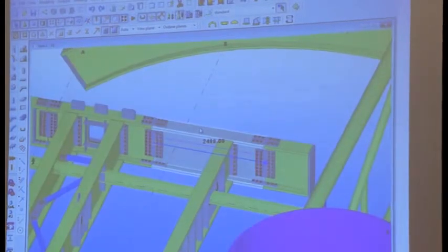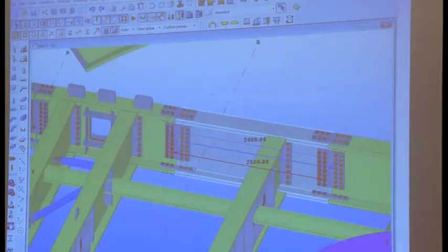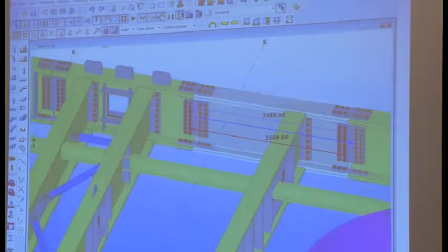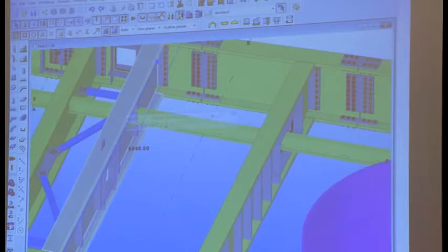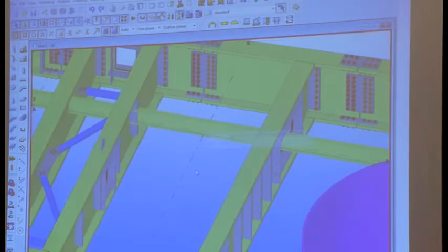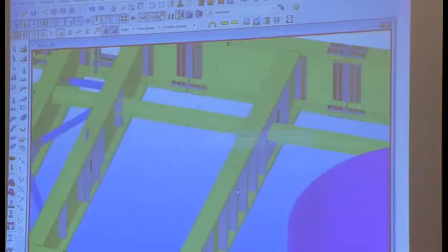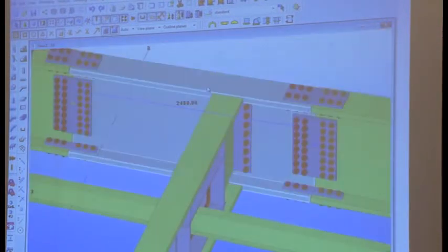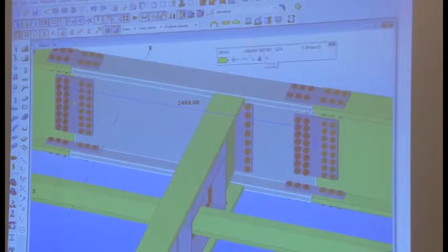Right, there is a beam with very heavy splice plates on it. Here's another one like this. Now typically what happens, I'll just do a control V. If that was built, at the moment, as you can see, that's a 106-305. But let's say I want that to be made from plates, 3 plates, a built-up beam. Okay? Now, if I want to make that from a built-up beam, I have to put 3 plates in there,